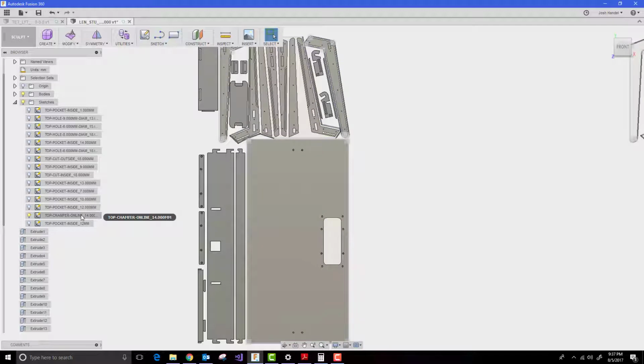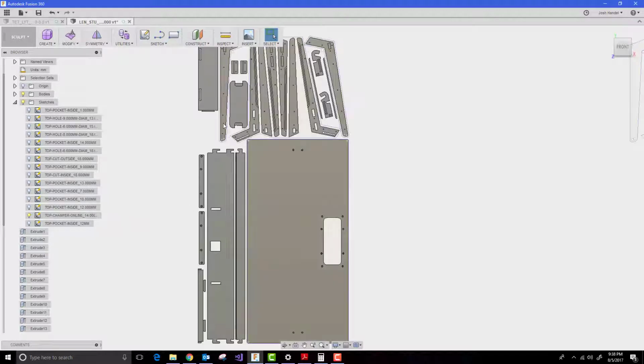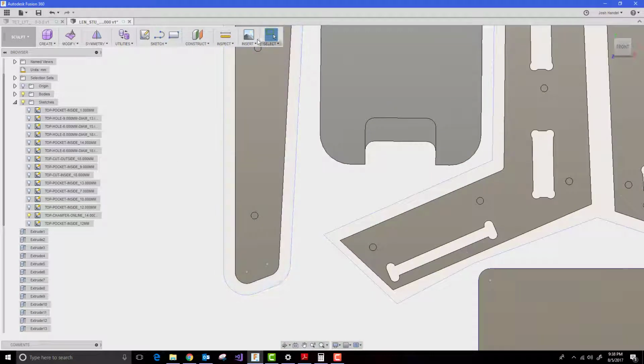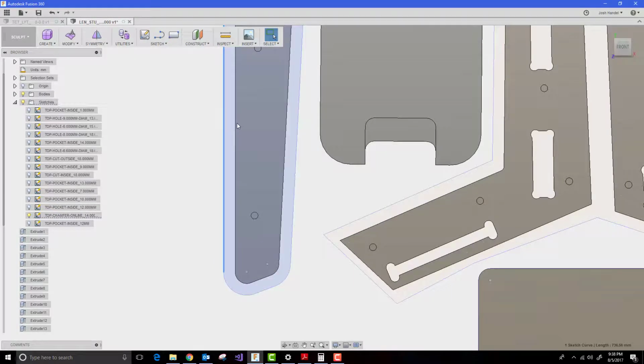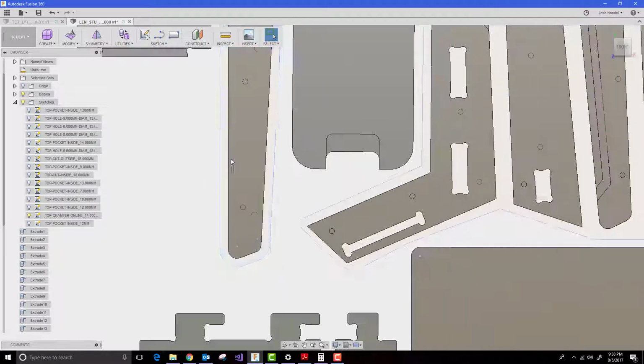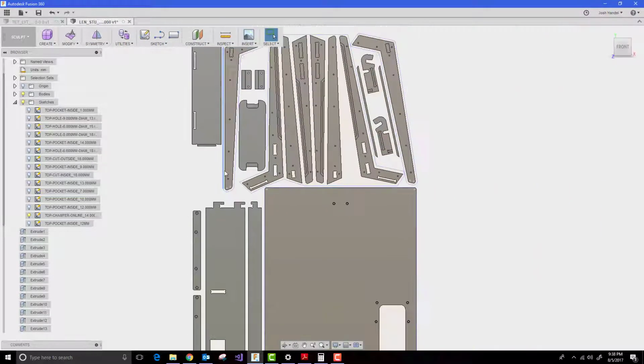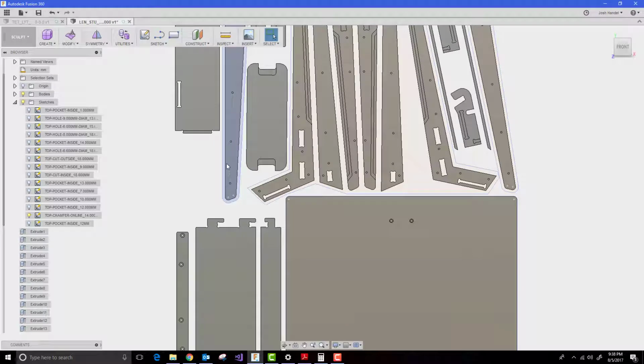ambiguity on what they want you to do there, but what they do want you to do is program into your CAM a chamfering bit, drop it 14 millimeters, and make sure it's wide enough to touch the material. So if we measure, say, here to here, it's not going to let me measure that. Anyways, whatever that distance is, they want it to be at least that wide and 14 millimeters down. Obviously you can be wider than that. You just have to make sure it's that wide.